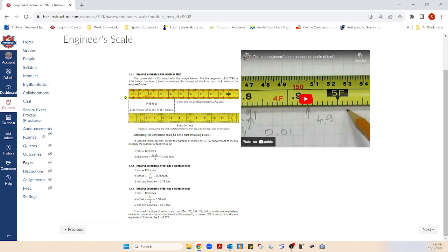This is just starting at the bottom, so it's 0.1 feet here, and this is hundredths, so it's 0.15 feet here and on down the line. Once you see this video, it's really good. It'll be this right here, in red like on a grade rod. He knows it's 4 feet. The beginning of this ruler is way down here.